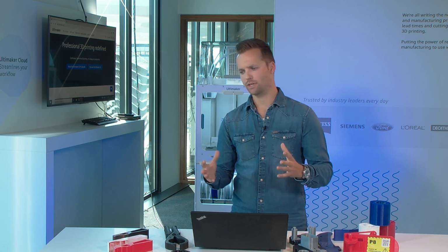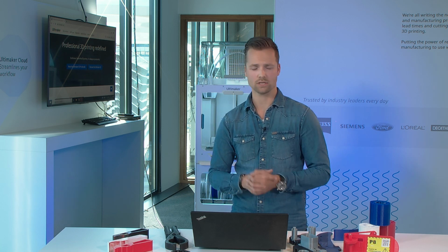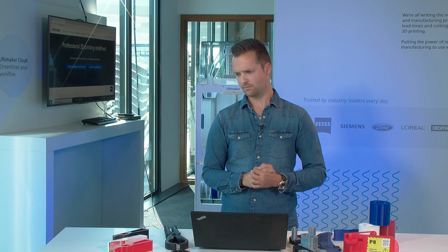And what I personally do, that's a tip from an application engineer, is to use horizontal expansion, where you can incorporate a certain offset while slicing your model. There's a new feature which is hole horizontal expansion, so this only focuses on the holes, for example, to make them slightly bigger or slightly smaller.